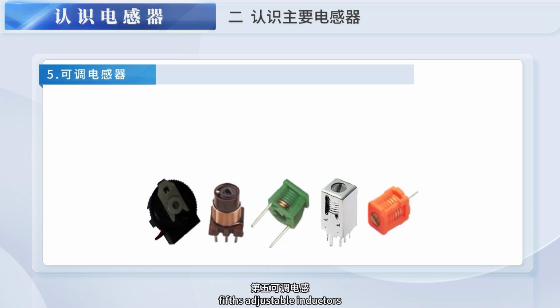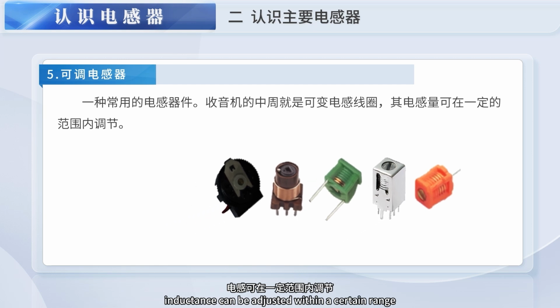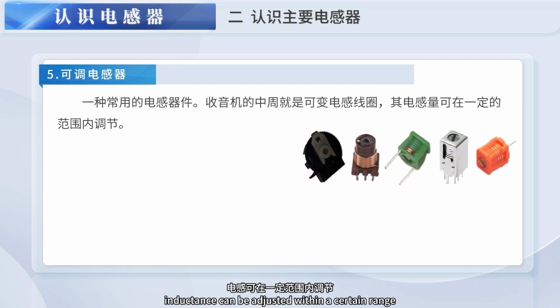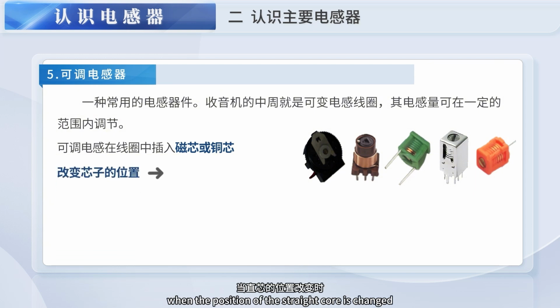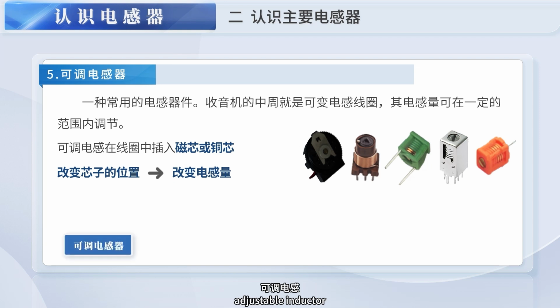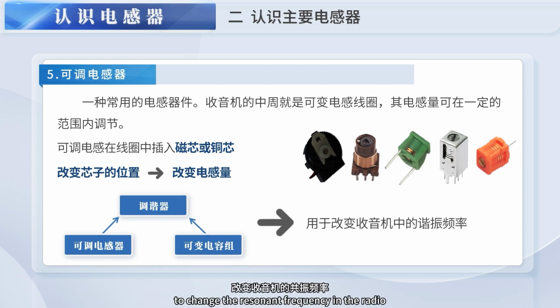Fifth, adjustable inductors. Adjustable inductors are a common type of inductors. The intermediate frequency transformer in a radio is a variable inductance. Inductance can be adjusted within a certain range. An adjustable inductor is inserted with a ferrite core or copper core. When the position of the core is changed, the purpose of changing the inductance can be achieved. An adjustable inductor can also be combined with variable capacitors to make a tuner to change the resonant frequency in the radio.